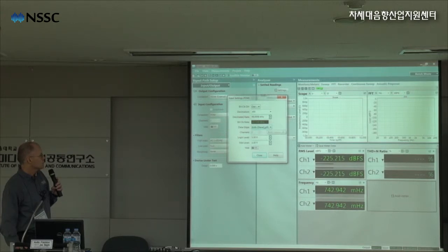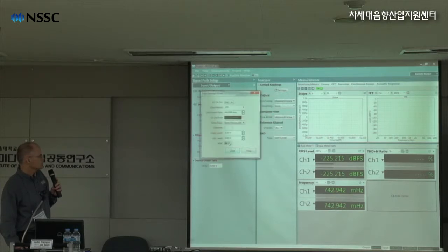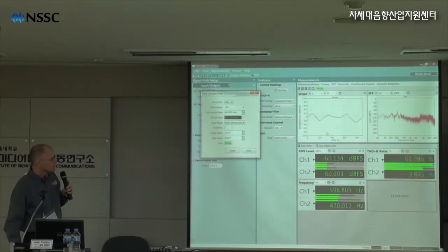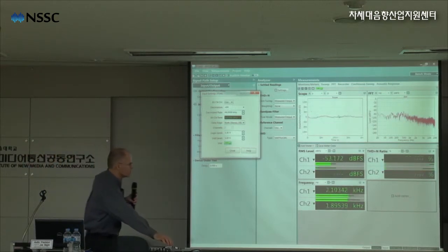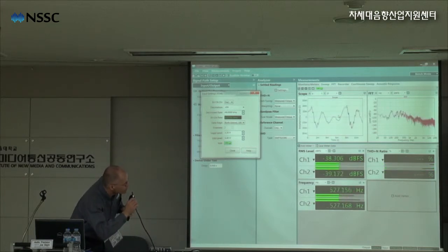And you can see that the bit clock rate for that sample rate with 64 times interpolation is 3 megahertz, 3.072 megahertz. So let me turn on the VDD signal, and we should be seeing a signal from that PDM microphone. So you can see the frequency over there. So these are basically just working like a microphone now. It'll be picking up my voice.